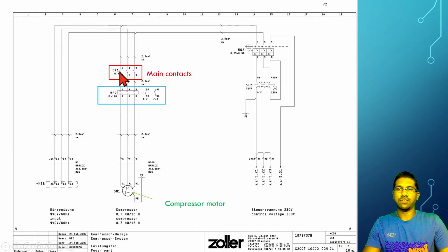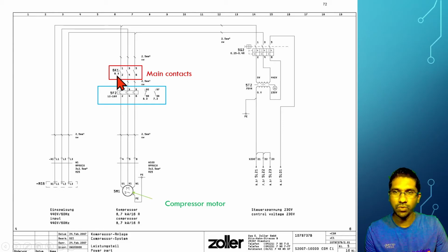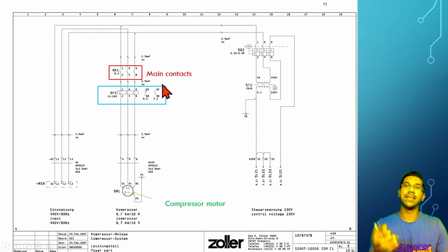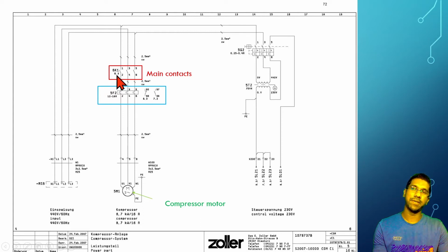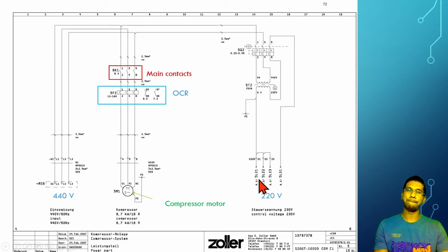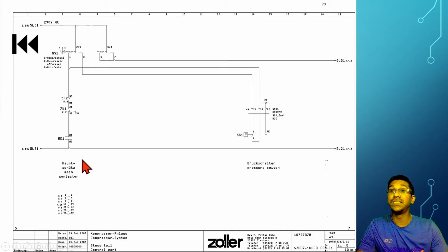If you want to refer to the 6K1 relay, then you can come to know how this relay should energize and under which sequence. So we will move to find the 6K1 relay coil. You have to refer to page number 6.3, that means page number 6, column number 3. Now we are on page number 5. Then we will move to page number 6. This is page number 6, and the column number was number 3.